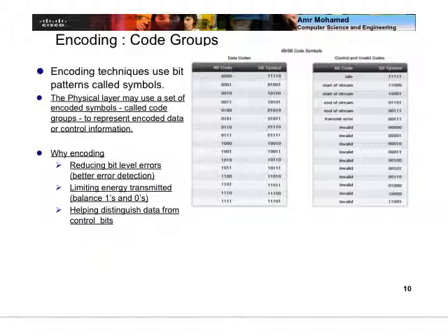For example, imagine I have a continuous stream of zeros using non-return to zero signaling. This will be a continuous 0 voltage signal, right? If you take the 5-bit symbol, then the 4 zero bits become 4 ones and 1 zero. So you have introduced a 1-bit change.